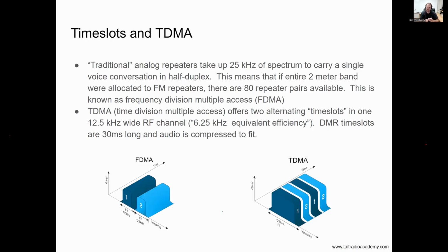The other thing about it is I mentioned amplifiers. Our conventional VHF or UHF brick amplifiers are generally designed for keying up and staying keyed up, and for FM, those won't work for the same reason.